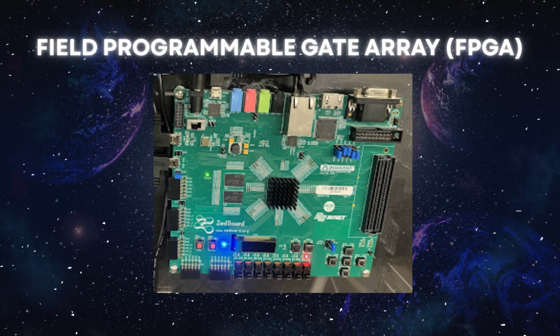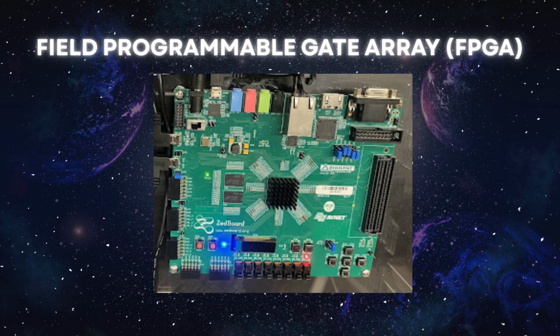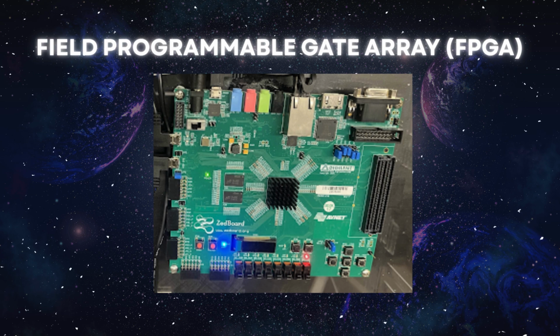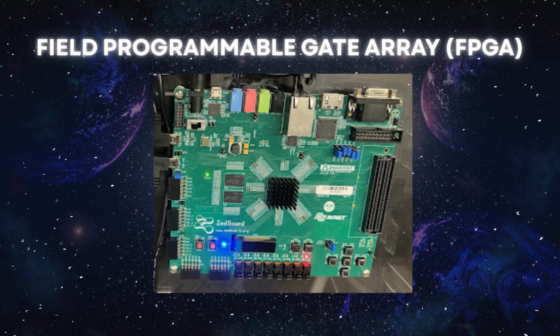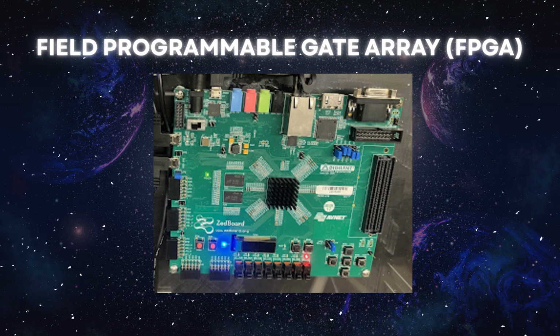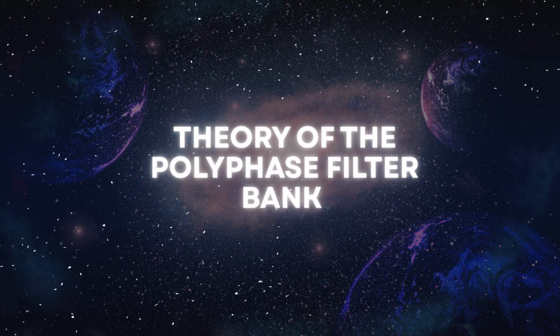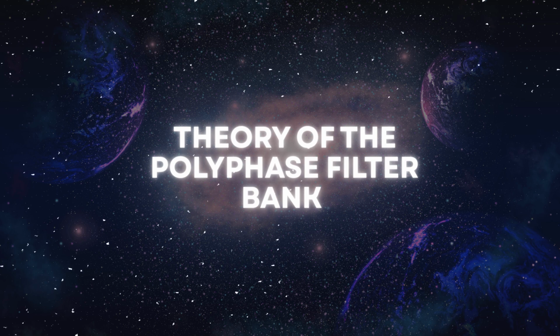Using Xilinx's HDL code generator, we produce Verilog code for FPGA implementation. Currently, we are conducting hardware testing and verification, with the next step being a hand-coded VHDL implementation to meet NASA's rigorous space flight requirements. Now we're going to talk about the theory of the Polyphase Filter Bank and how we